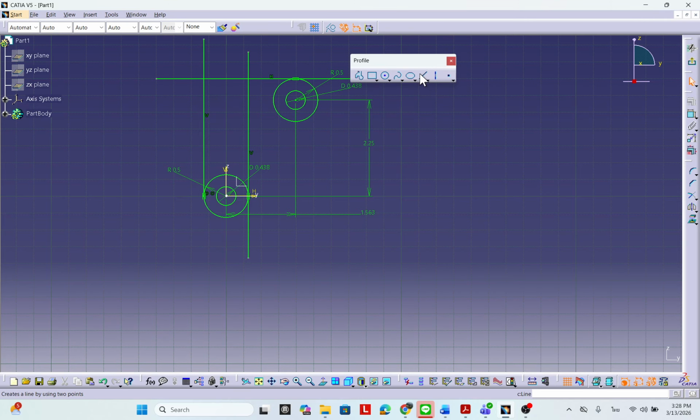And as I told you, you should avoid the constraint being generated automatically, right? Something like this. You just click the start point of the line, you click on here, and the constraint. Think about it: you need to create the constraint over here, click on there, right?